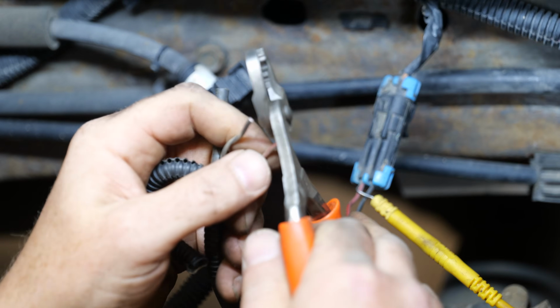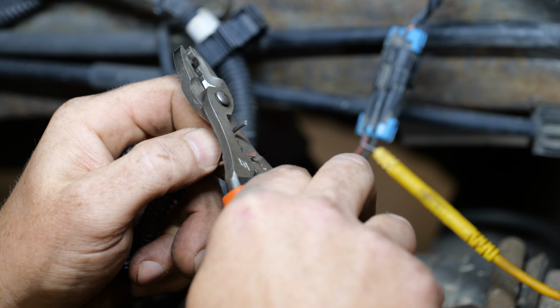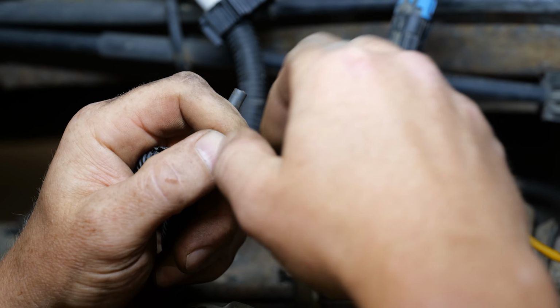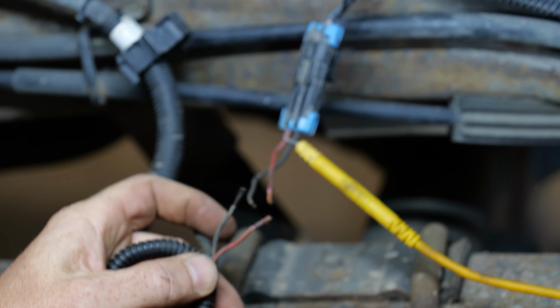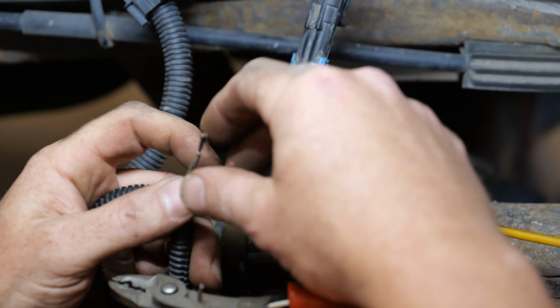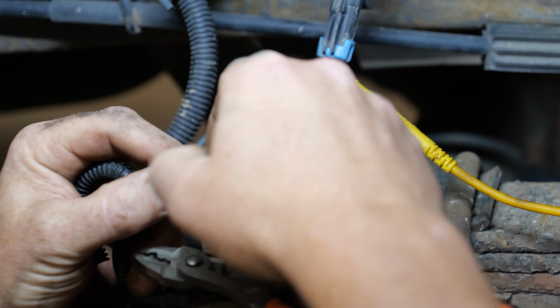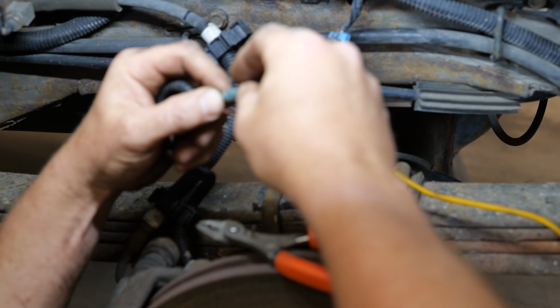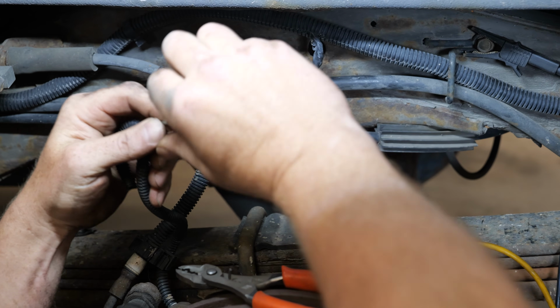I might have to put an extension piece in here. You can't solder wires when it's like this. I wasn't going to anyway. We like our heat shrink butt connectors. But when they turn black like that, that's adding resistance. I know you can clean the surface a little bit. This is going to be a temporary fix just for this video.